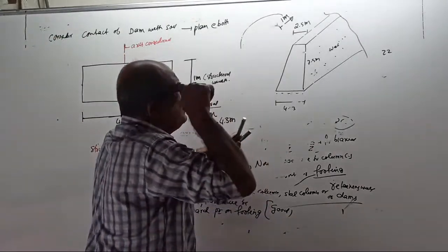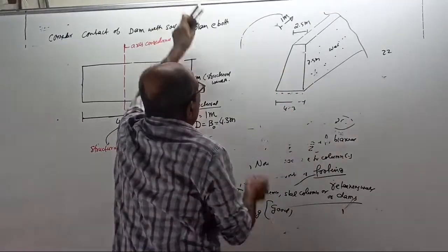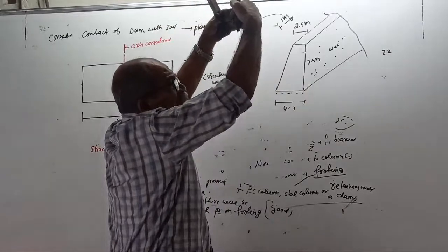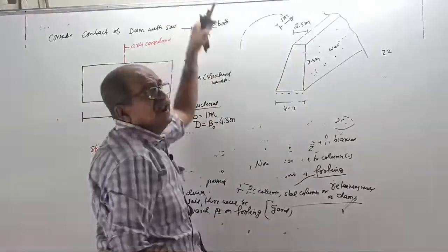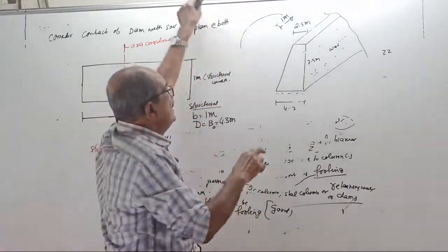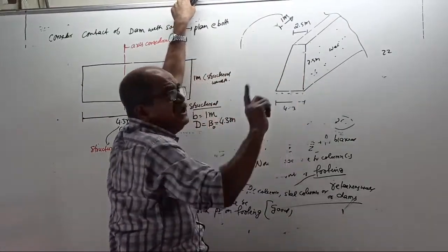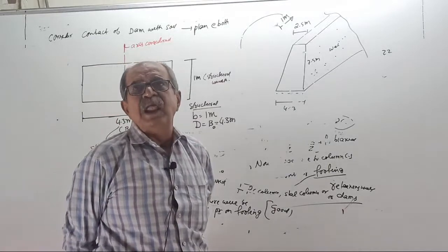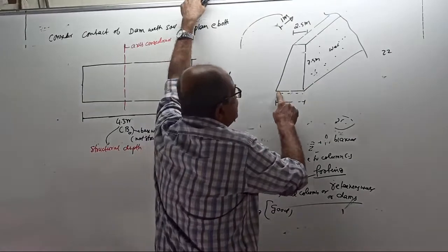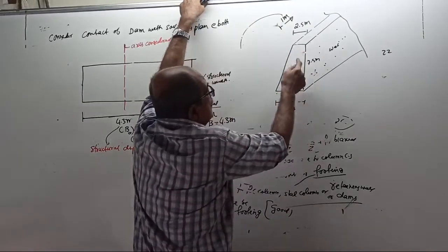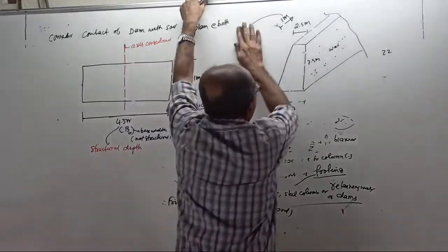Now, when I calculate loads, first I will calculate vertical loading. I will remove the sketch. When I take vertical loading, this weight has one rectangle and one triangle. You cannot take a trapezium, because the CG formula for a trapezium is applicable only for CG measured from one of the parallel sides. But we want the center of gravity this way, so the formula is not possible.